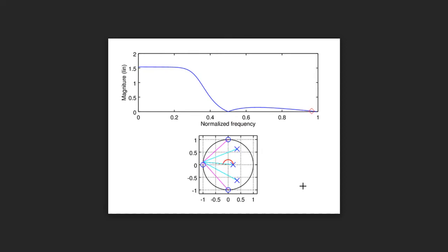Except, okay, this frequency space is differently mapped as in analog systems. On analog systems, the Butterworth filter poles are where? You should remember that better than I do. Okay, S-plane analog system. Here we have the omega z or j times omega z, minus j times omega z. Does this one ring a bell?